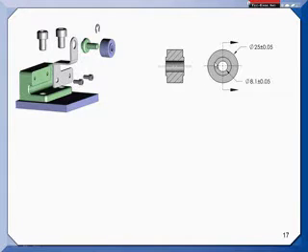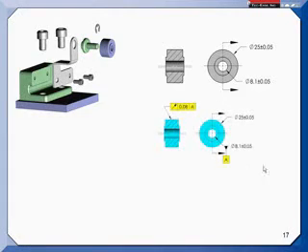So I might start with the roller and using our criteria. Who would I choose as my primary datum feature? And since a lot of you don't have microphones, I guess I'll go ahead and answer it. As I look at the assembly and ask what feature on this roller is going to end up constraining the degrees of freedom, I'd say it's that inside diameter. So I'd be very tempted to make that my primary datum feature.